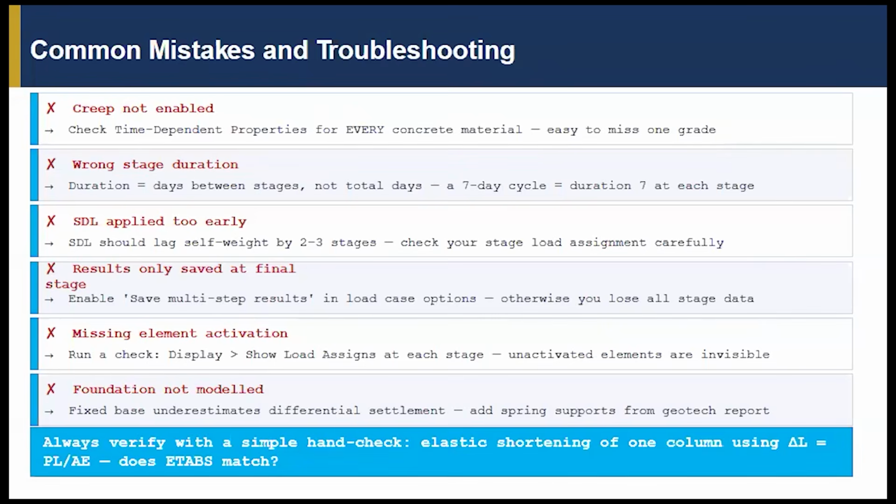The structure wasn't complete. Foundation not modeled. So we just modeled a fixed base. Like I said, soil structure interaction is a separate thing we will discuss, but that also affects this one because construction sequence with foundation settlement becomes more important than without that. Because now the construction and the settlement are combined together because of the interaction between soil and structure over time.